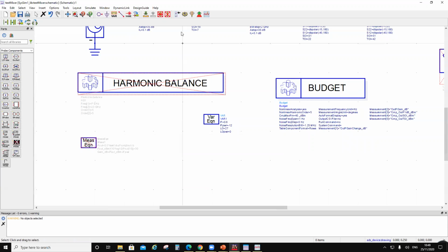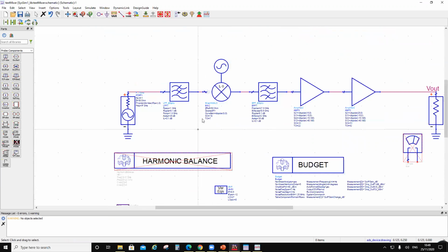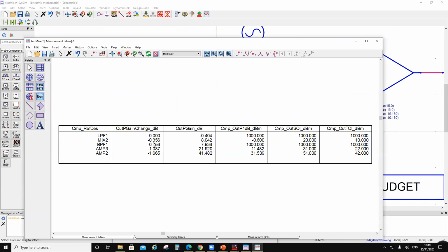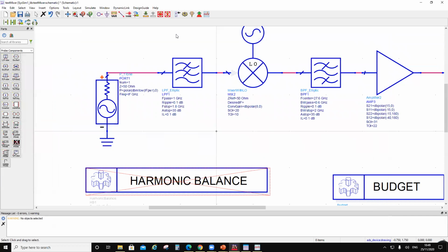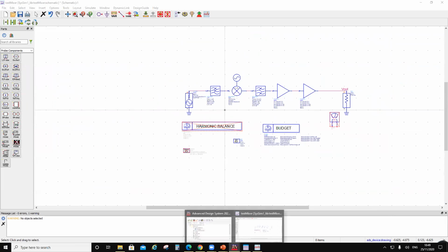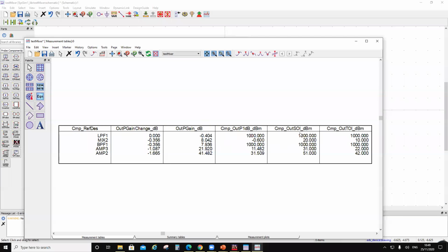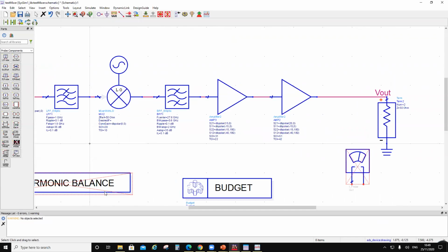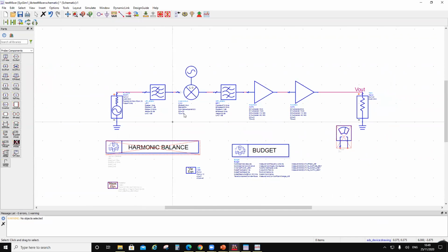Now the mixer is 0.35 compressed, right? Now the amplifier is 0.6 compressed. So let's look at the power delivered. P1 dB is around 31, so it should be able to deliver power. The mistake I made again was assuming 22.5 gain. It was 15 gain. That was the problem computing this.